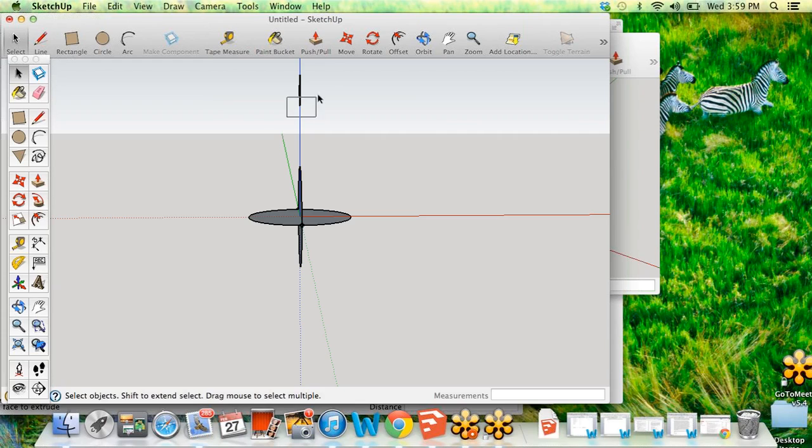My next step is to move around with the orbit key, use my select tool, delete that first circle, use my circle tool again. You'll see this circle is green. Press my Shift key, build my example circle, go down here and select the center. Now I can let go of my Shift key, and I have my last circle. I'm going to use that endpoint.